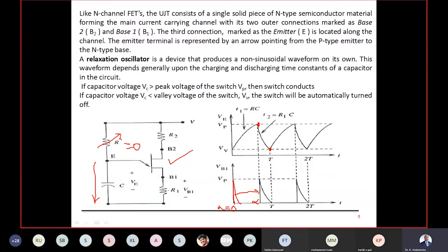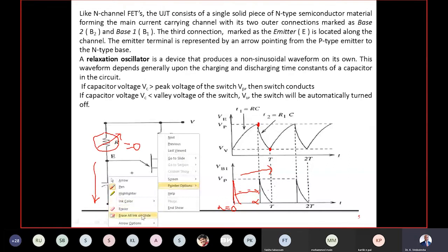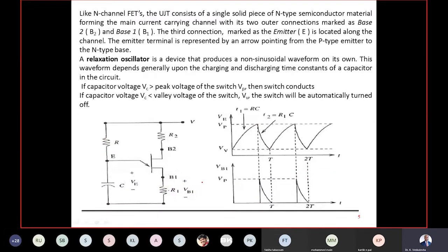When you keep increasing the resistance, obviously this pulse will keep moving to the right-hand side. I can set 0 degrees, 10 degrees, 20 degrees, 45 degrees, up to 180 degrees. So in the experiment, by varying this resistance we vary the firing angle, and we see how the output DC voltage varies. It will be reduced; how it will be reduced, we will see. So this is the highlight of this particular circuit.